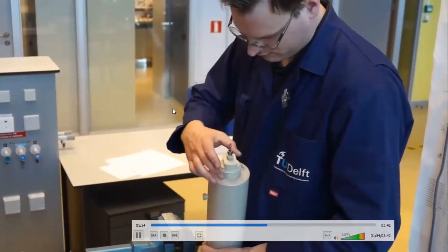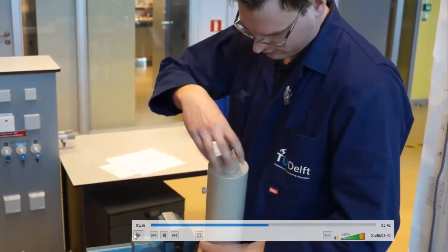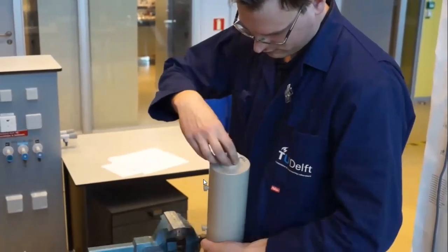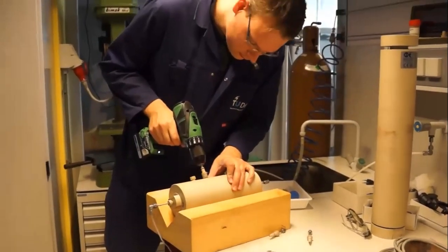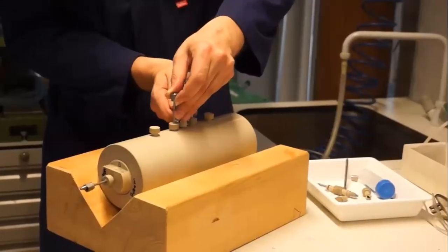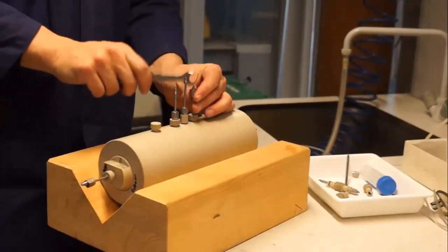We drill into the side of the core holder. This is now the core holder. They put the sample inside, the core sample. They will close it, and then they will add taps, which allow us to measure pressure. This is important to make sure that we've obtained the conditions we want and also to see how easily the fluids are flowing, how much pressure they build up as they flow through the core.